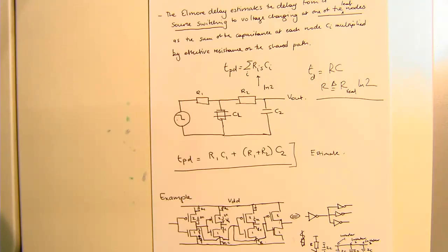For example, as we'll see later on in this lecture, there are some gates which are more expensive in terms of propagation delay than other gates. So even though you've learnt potentially in your second year or third year, somewhere in the master's course, how to rewrite some logic functions, really what you need to be doing is, for example, if you had a truth table, how to derive the equivalent circuit.